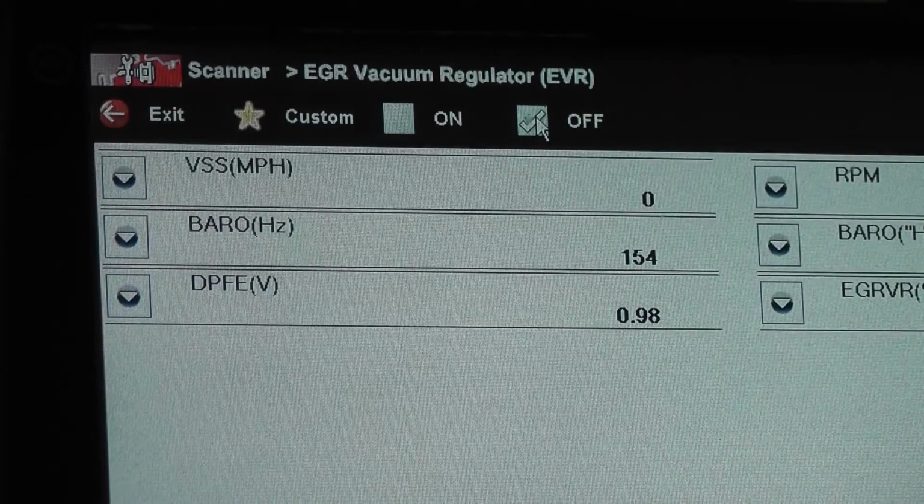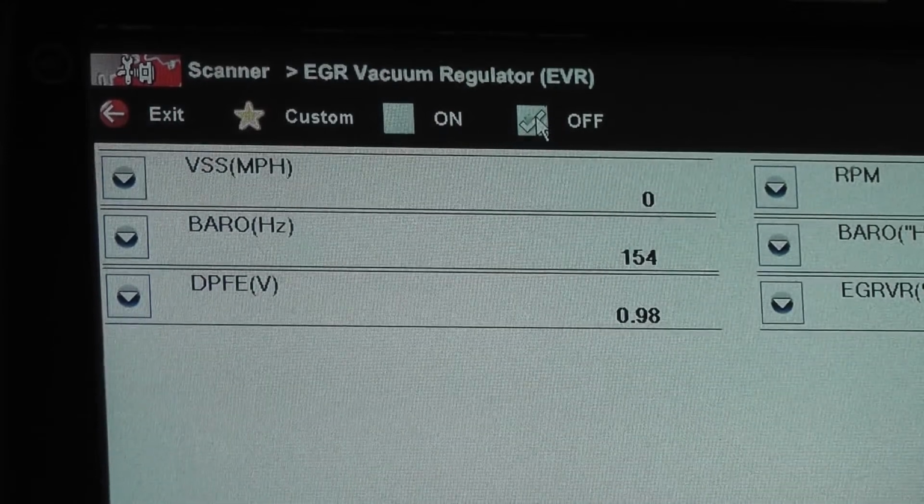And we're going to see if our test light lights. If the test light lights, that's going to tell us that that control circuit is functioning normally. Tells you the control wire has no opens. And also tells you that the driver's functional. And that's what we're worried about. So we'll go down to the connector and take a look.